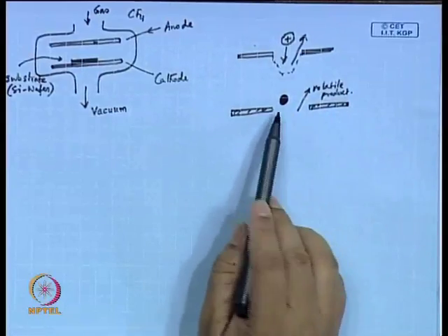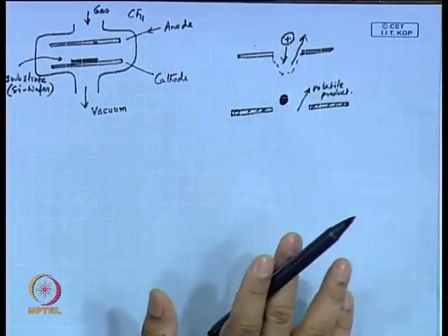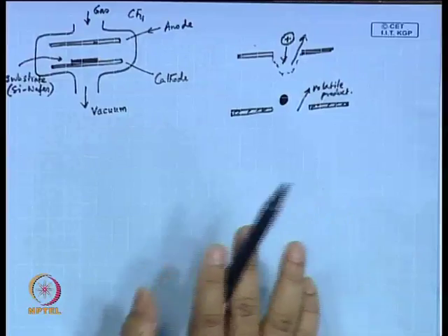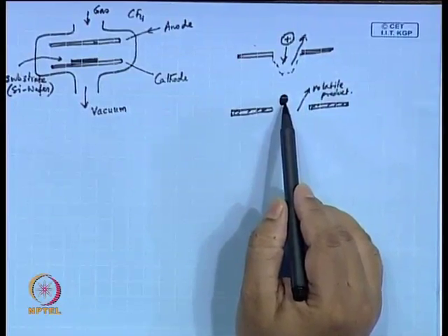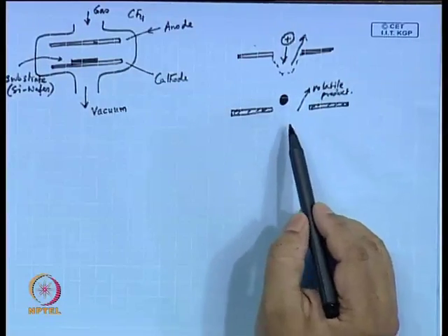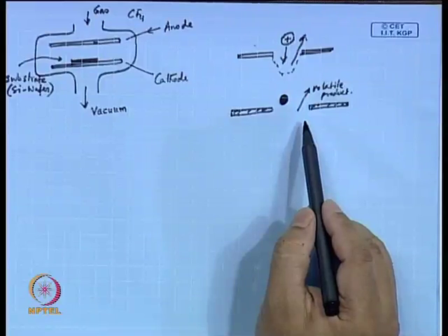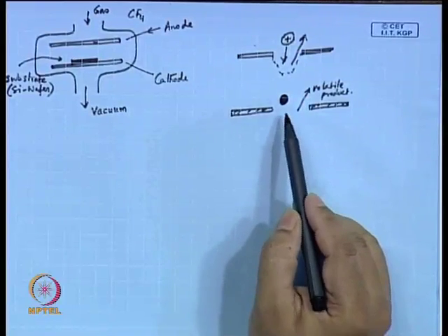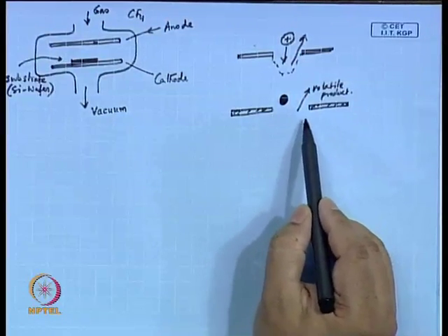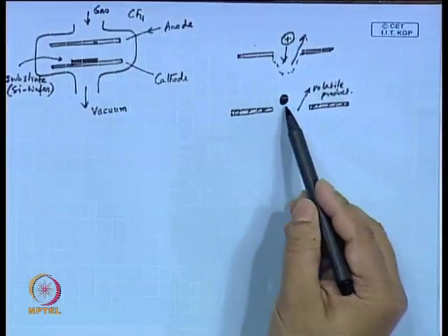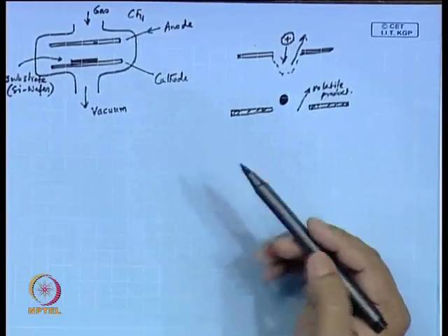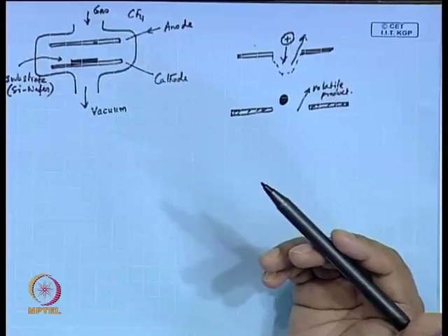So, here this is not a ballistic ion, I mean this process does not involve any ions bombarding the substrate. So, how is this XeF2 coming in contact? Suppose I have etched some portion. Suppose I have formed a cavity already, but I am making it deeper. So, how is this XeF2 getting into that cavity for further etching? It is by diffusion only.